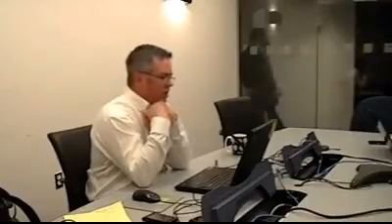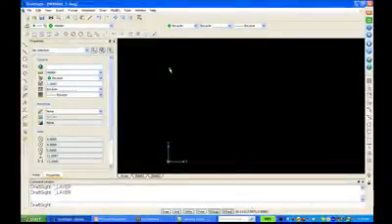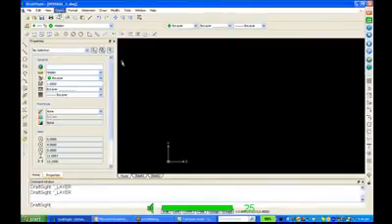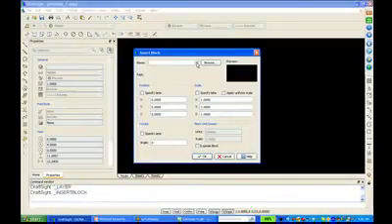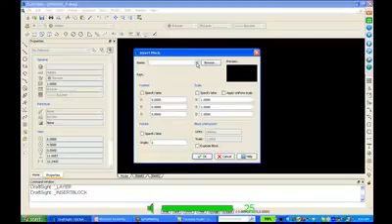I'm going to load in some preset drawing formats that I've created. I'm going to bring them in, and I'll store them as blocks. Right now, if I click on Insert Block, I have no blocks assigned to this file. What I'm going to do is create some blocks, bring some blocks in, and save them in the file so that anytime I open up a new file and I need to insert a drawing border, I can just go into my blocks and insert it.